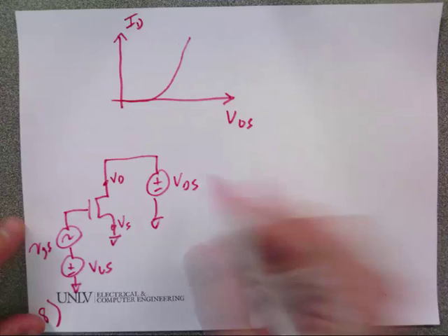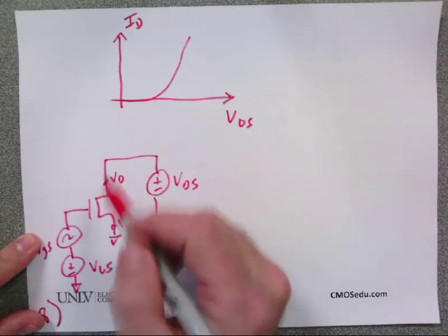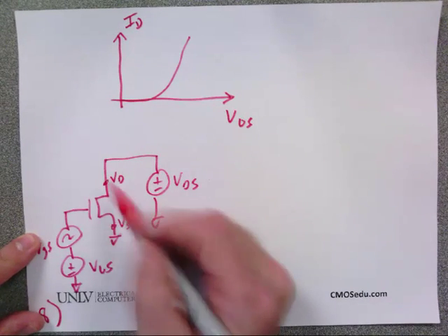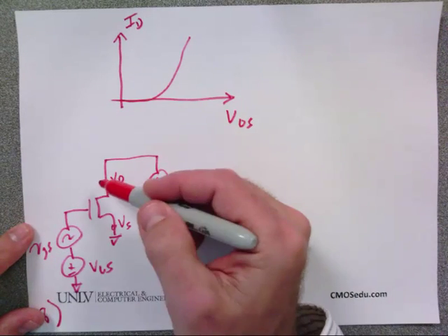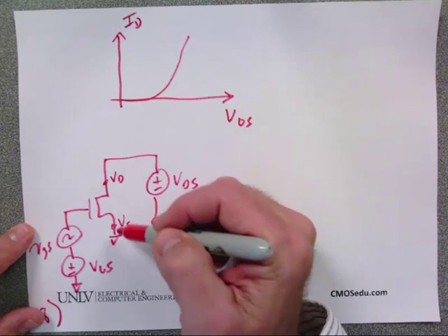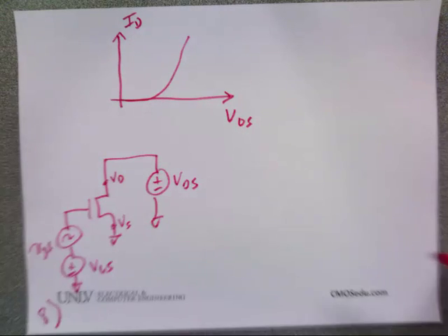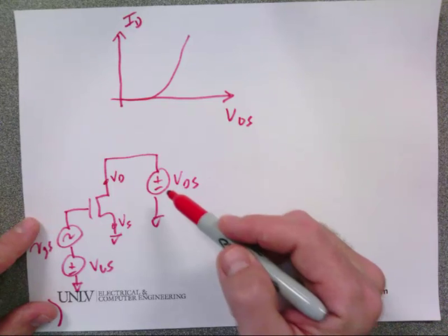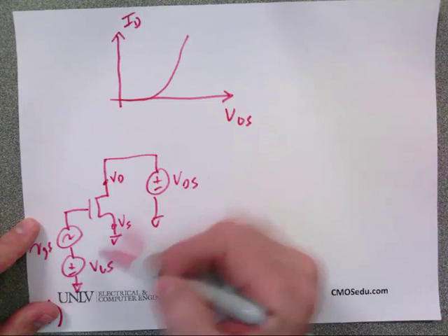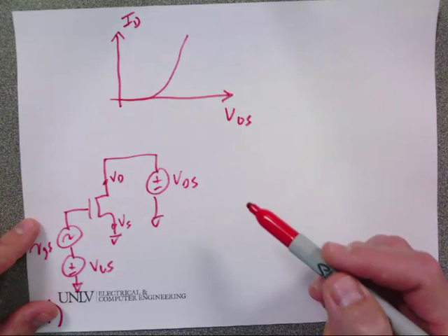Okay, in this case I could call it VDD because I don't have anything, but it's more technically correct to call it VDS. Don't get hung up on the names unless it's directly between the drain and the source, then it is VDS and you can't change it. But I mean, you could call it VDD, and VDD equals VDS.